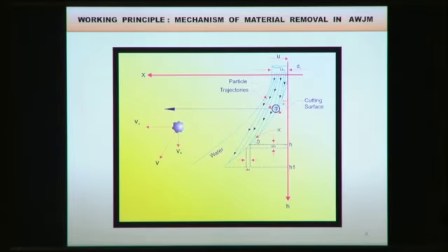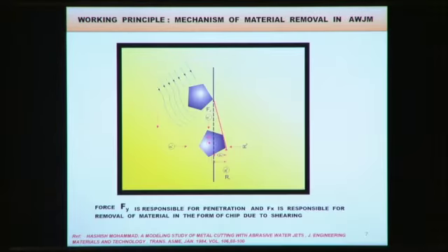So here abrasive particles are coming with an angle, hitting the workpiece surface. There are two forces we can see here. This force Fy is responsible for penetrating the abrasive particles into the workpiece surface. Another force, Ry, is the resistance force by the workpiece. So Fy is balanced by this resistance force.